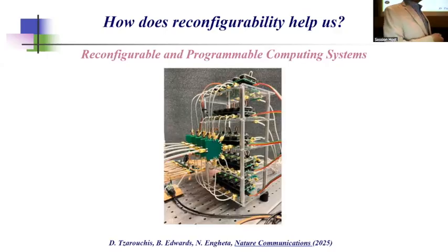In this system that we built, every one of these elements can actually be controlled independently. So in other words, you can think about this as a 5 by 5 matrix where every element can be changed independently. So this is not a Swiss cheese or anything that the wave interacts with. Each is just independently controlled. Then, as we learned from our previous work, if you take an output of this and feed it back into the input, you would be able to actually invert the matrix. And that's exactly what we did, with the waveguide system bringing it back over here and combining the signal.